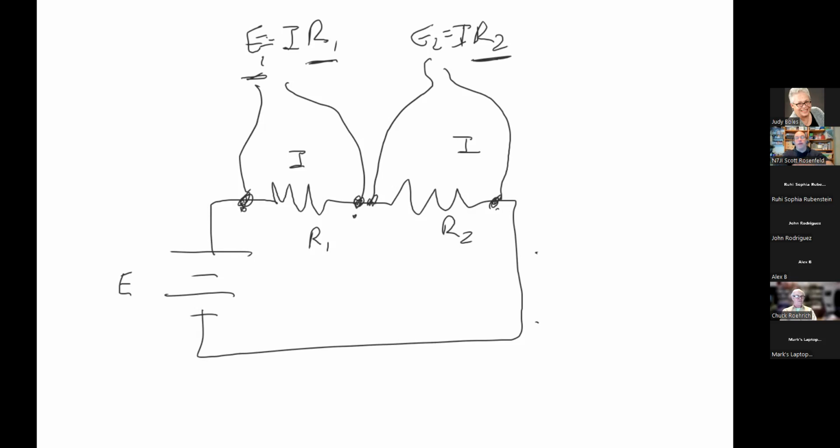That's my question. So if I have an extension cord that's 800 feet long, the drill on the end of it won't work. That's exactly right. Well, actually, what's happening is that the resistance of the extension cord is using up so much of the voltage.